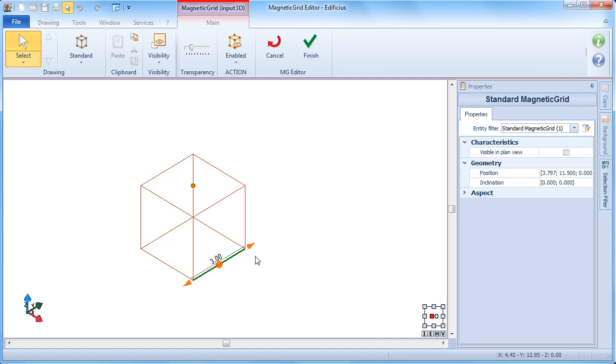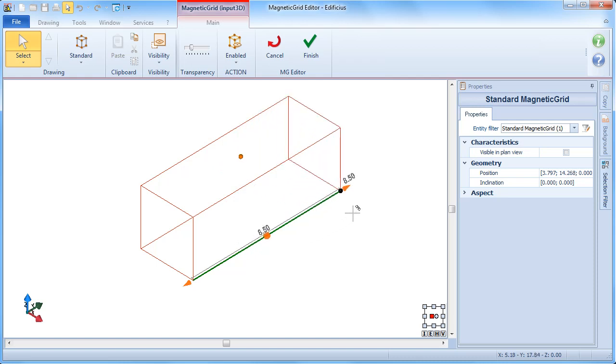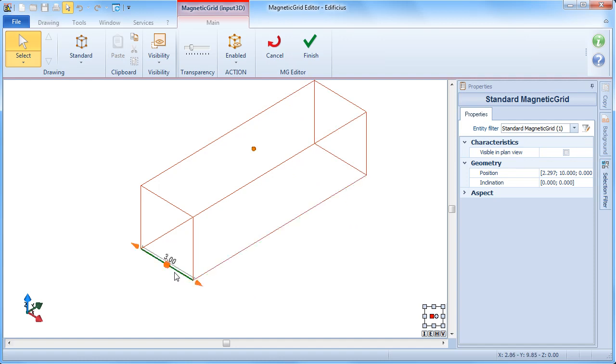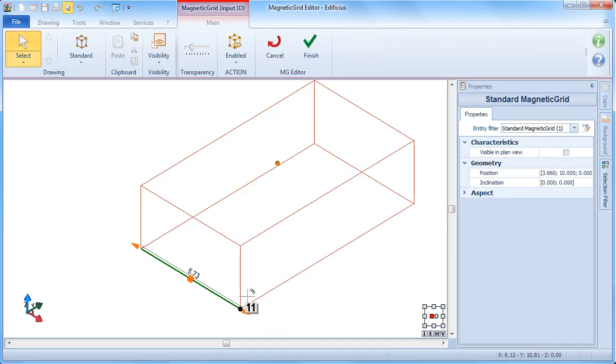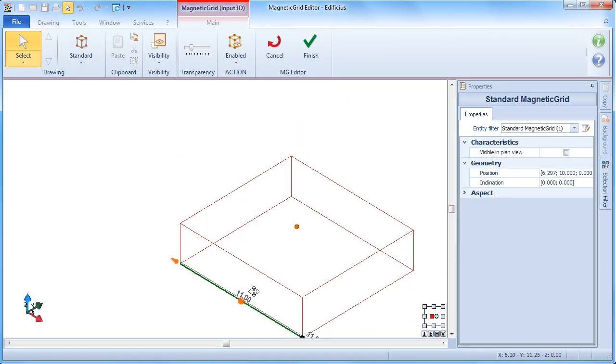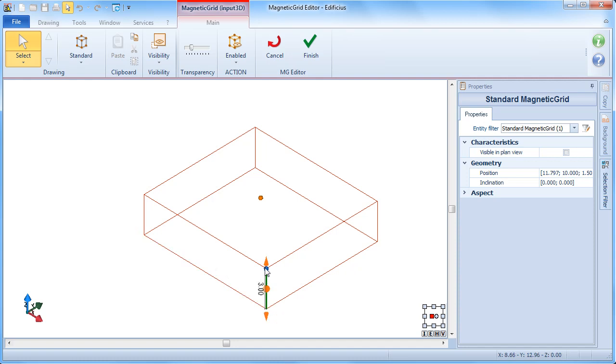In fact, at each of the ends of the selected segment, we have the arrow grips that, if clicked, activate a local menu. If we slide the grip point up or down or across, we can change the segment length, or we can directly type in a value from the keyboard. In the very same way, we can proceed to modifying the segment height by simply changing the length again.